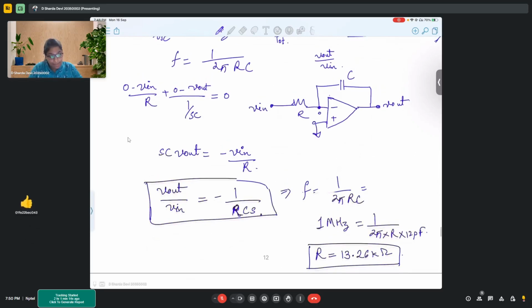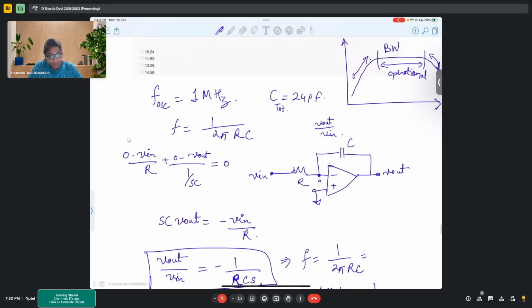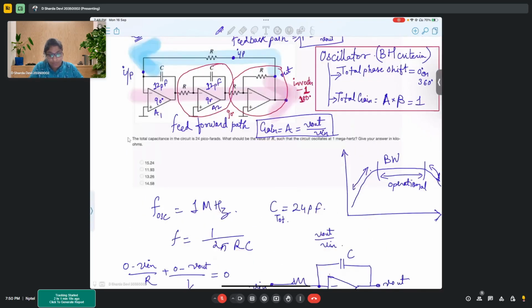Yes. Just one question. You said these will introduce two poles. Without calculating the function, can we know, with a quick look at the circuit, whether it will have two poles or two zeros or something like that? I mean, it depends on practice. If you know that this is a low pass filter circuitry, then you know that in a low pass filter you will have one pole coming into the picture. Whereas if it was the other way around, things would change.